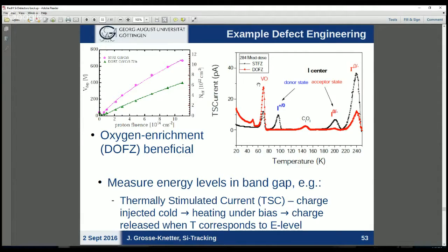So basically by forming special states inside the lattice, the oxygen is really made part of the lattice and can kind of conceal the negative effect of things like a vacancy or a displaced silicon atom. It will still create energy levels that were not there originally, but create them in a different place where they don't disturb us as much as they did before. And the net effect is that you see not as much of a negative effect on the effective doping concentration.